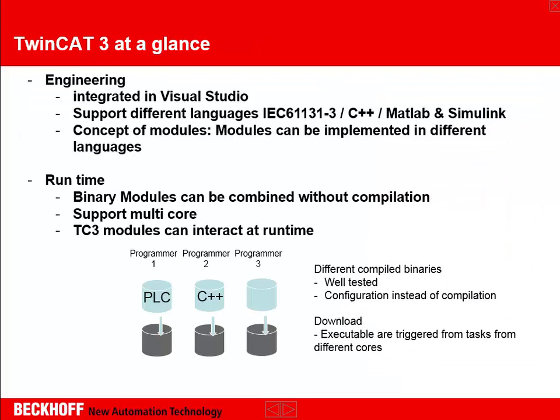First of all, as a quick start, let's talk about TwinCAT 3 at a glance. The engineering of TwinCAT 3 is integrated into Visual Studio. We support that you can implement the code in different languages, everything from IEC 61131, but also C++, which is a topic today, and also MATLAB Simulink.